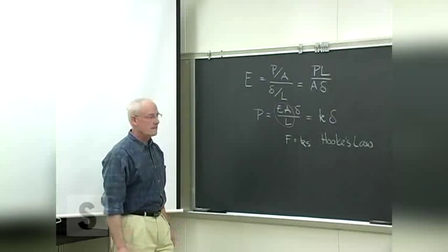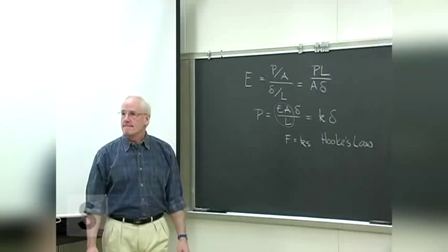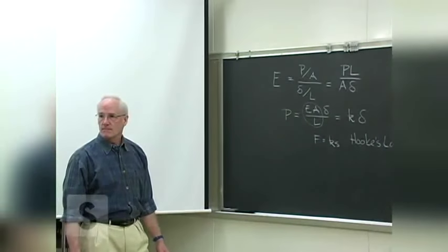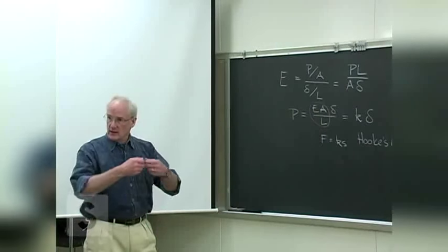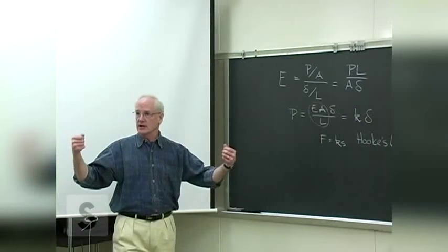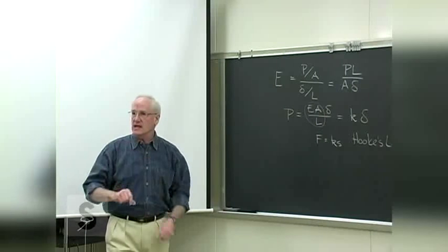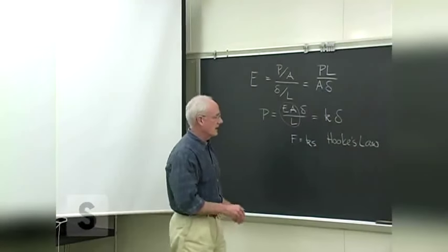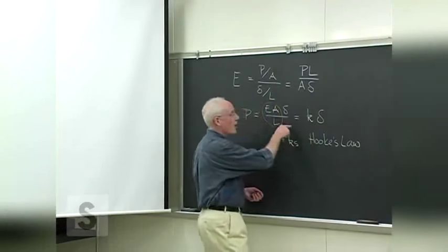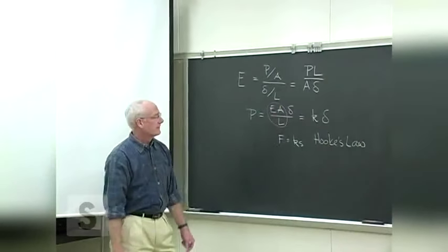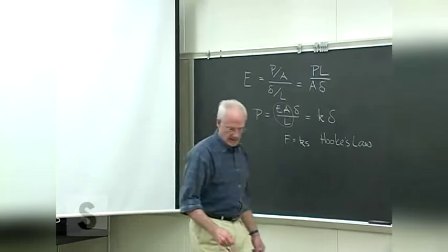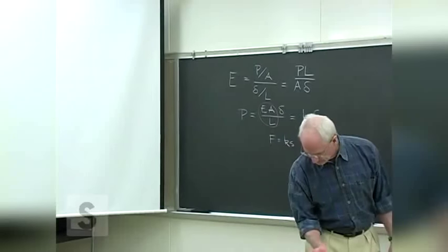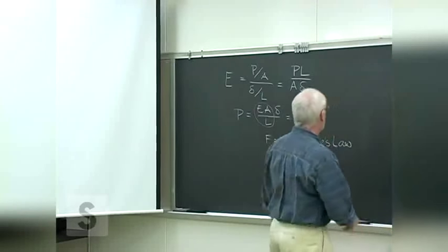And they also function out of tension. Springs are more off of torsion because the wire twists as the spring expands. Oh, yeah. When you put the spring in tension, the material is actually twisting more than simply elongating. Yeah, you're right. But the overall response of the spring and the pieces we're looking at in these cases are very, very much the same. Okay.